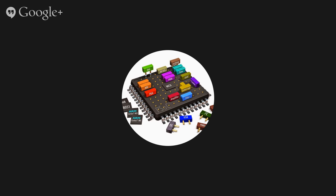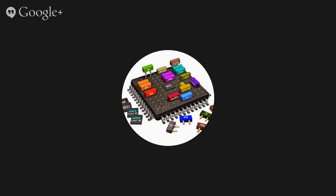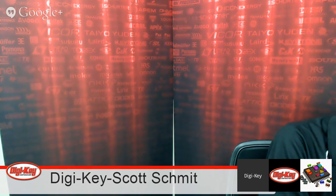And so now I can blink this on and off, like that. You can put another delay in there. If you want to find out about CyDelay, if you didn't know that was there, go to Help, Documentation, System Reference Guide. There is a system reference guide here that contains all of the Creator-specific resources that we provide for you, such as clocking, power management, CyDelay, that kind of stuff.